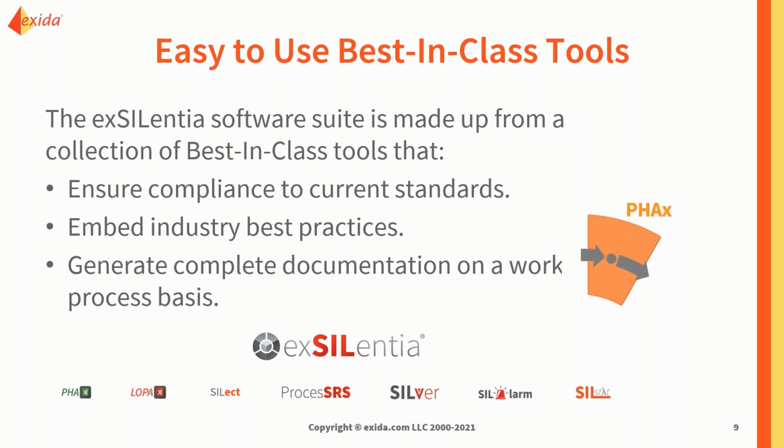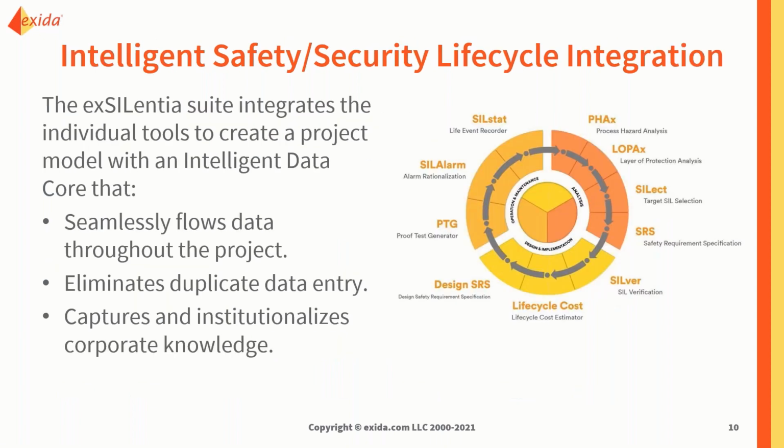And then later on, we tried to implement more and more into this tool, like PHA, LOPA, SIL select, and SRS information, SIL stat, and also SIL alarm, which is related to the alarm management part of the safety side of the operation. And because we have different modules linked together within one big tool, it's also easier to let information flow.